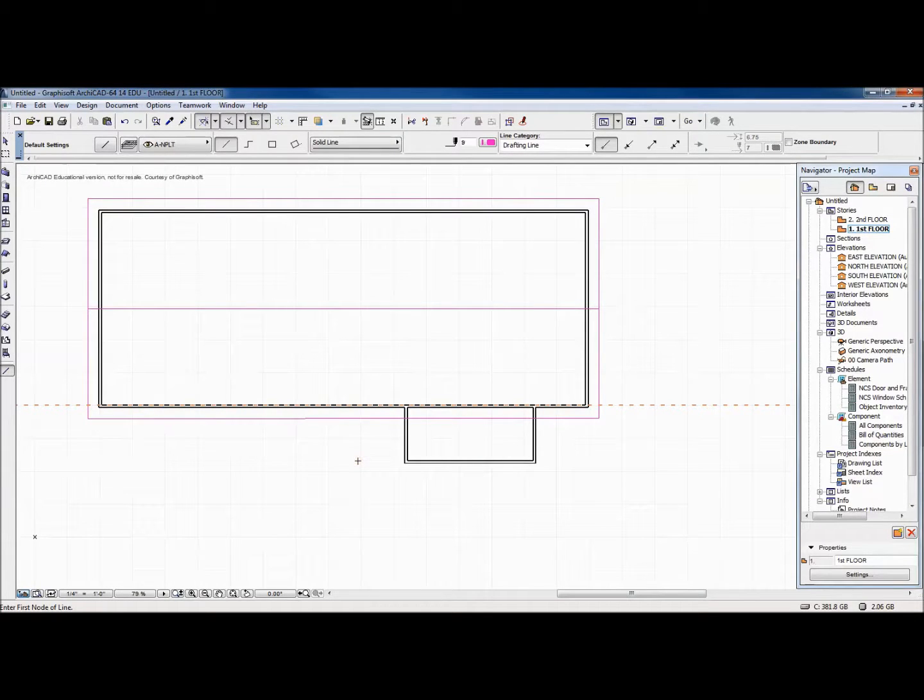So you should have had an opportunity to go ahead and build a gable roof and practice those skills. Now it gets just a bit more interesting when we go to put a dormer or a second gable to the front of the house. So basically what we're going to do, I've added this wall section here, and we are going to pull this out 16 inches again to maintain a consistent overhang.